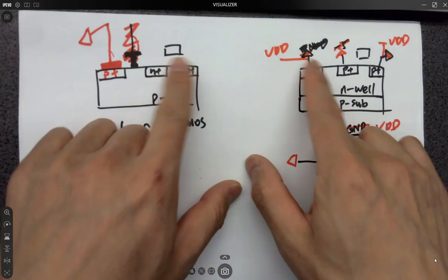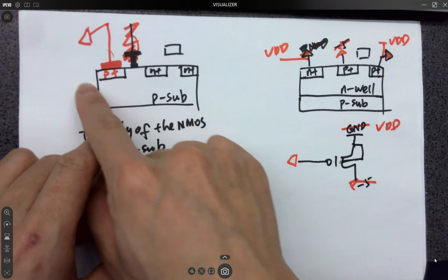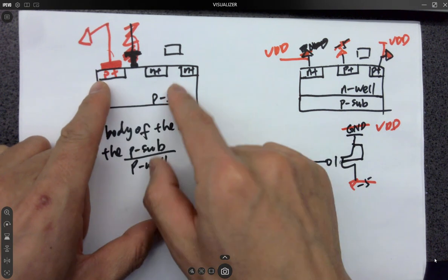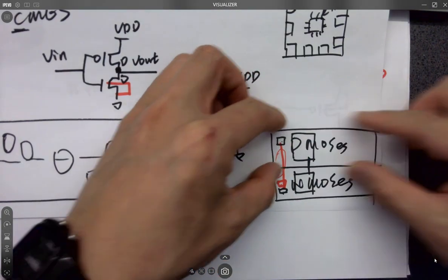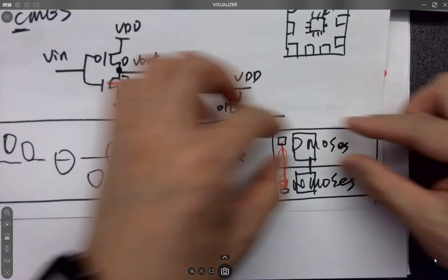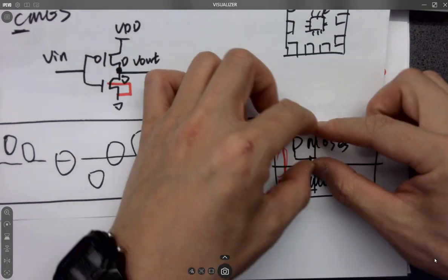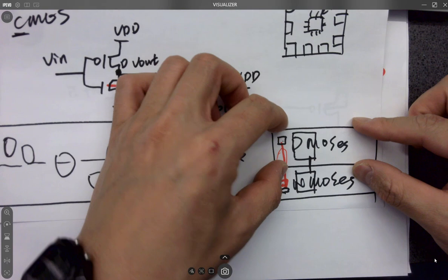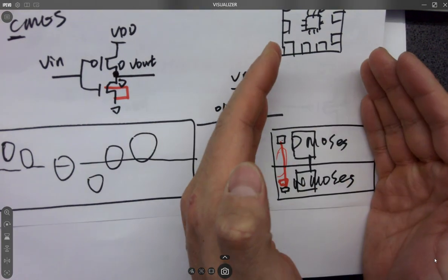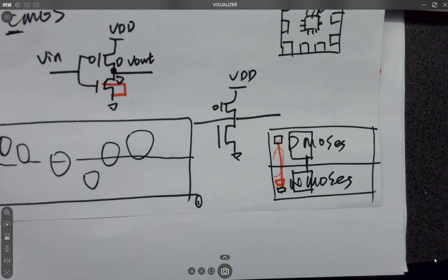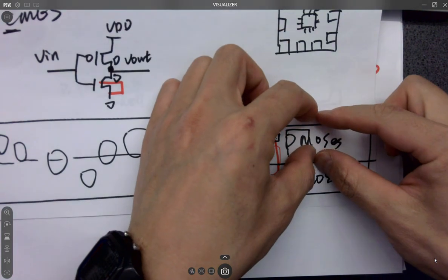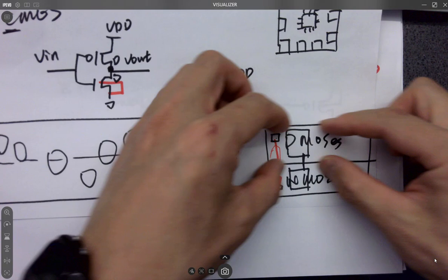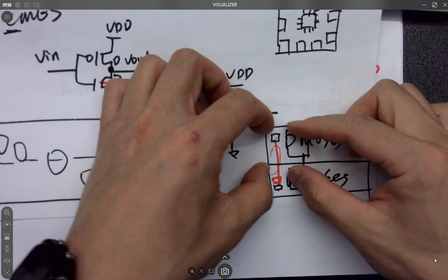So in that case, when you have everything fabricated in the same well for the PMOSes, you would like to place the big N well for all the PMOSes on the top. So this is the top view, right? When they are doing deposition, they are looking from the top and trying to do all the diffusion from the vacuum chamber into the wafer. It's pretty difficult to control. If you want to form a different shape of the N well, it's probably not a good idea.